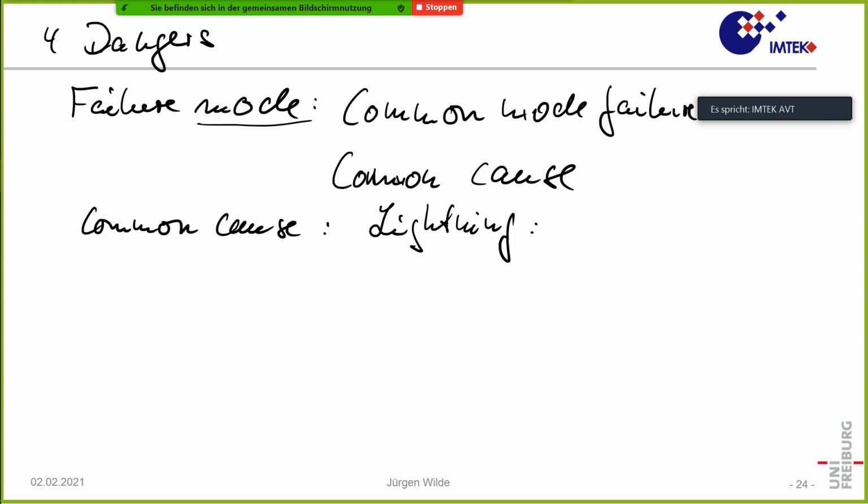That is typically called surge. That is when you have a high voltage on a power line or so, coming on all conductors, and in that way you can have a fault or even failure. Another thing is also electromagnetic burst. It's a similar signal to surge, but with another origin. That's for instance if you have an internal arc or something.